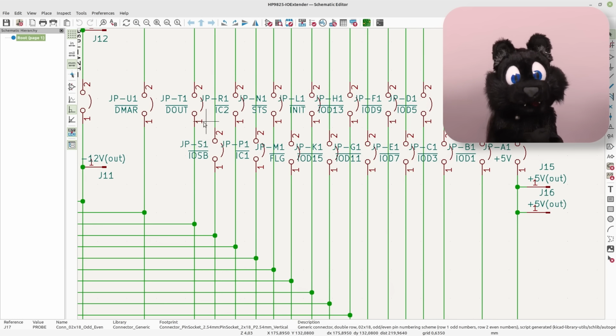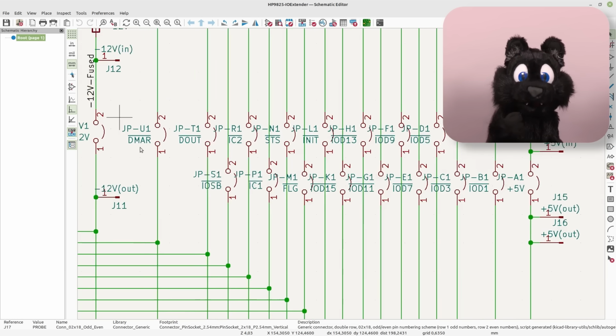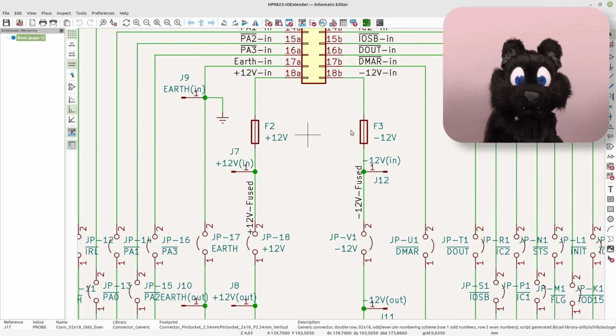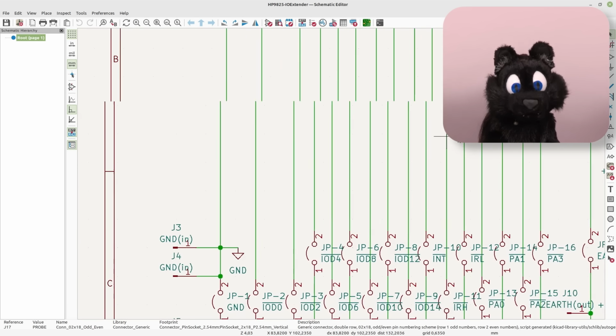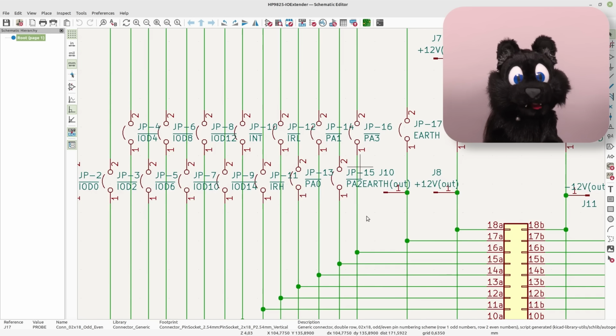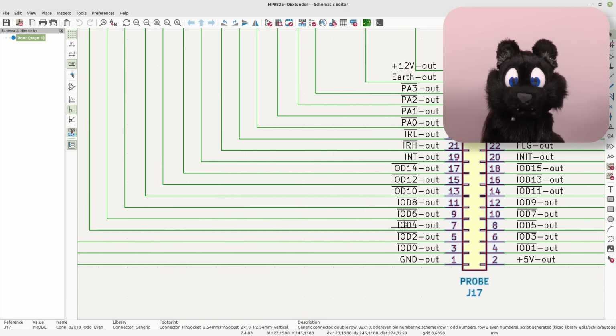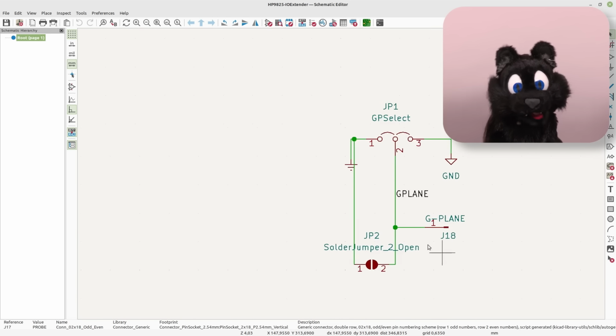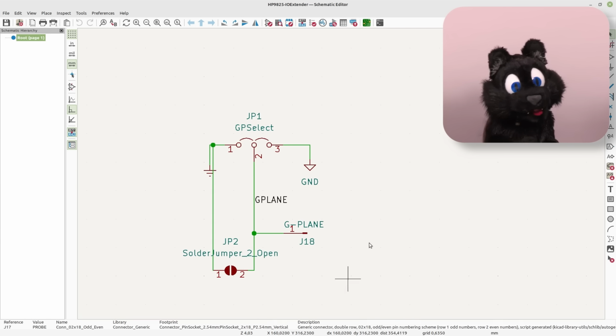Oh, and what if something fails? How about fuses in the supply voltage lines? Yes. And lastly, the ground planes of the cards are usually connected to the earth pin of the extender, not regular ground. I don't know if that's universally so, hence I make it an option.